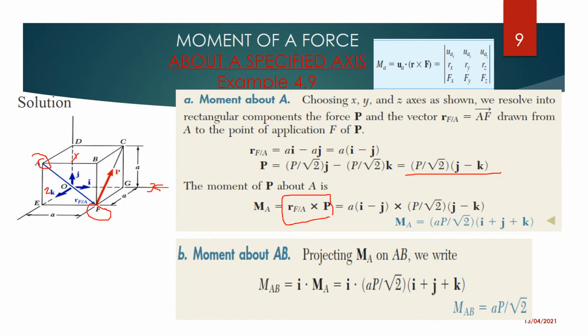Don't forget how to calculate the moment using the cross product. Can you remember how to calculate the determinant? If you can remember very well, here we need to have our i, here we need to have our j, here you need to have our k, instead of those unit vectors that you can see. Those unit vectors only work if you are using a triple scalar. But for now, for a cross product, we don't consider this. We're going to replace those with i, j, and k.